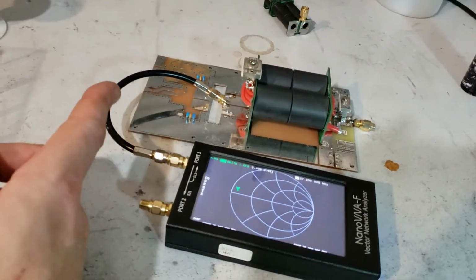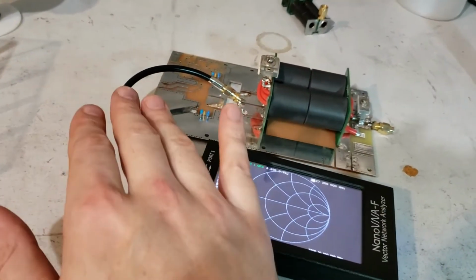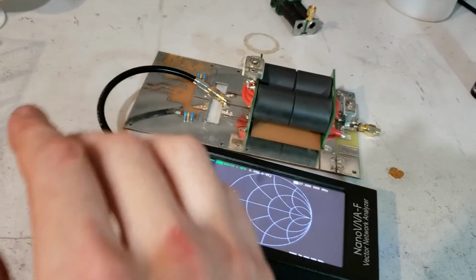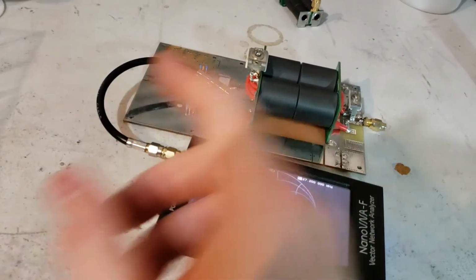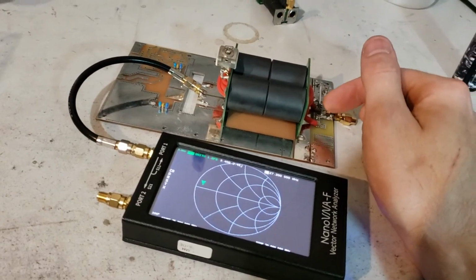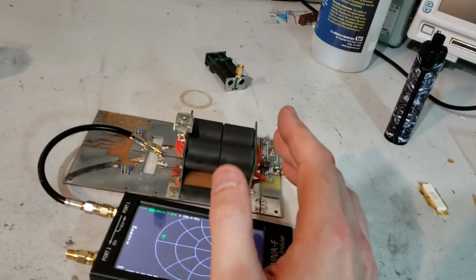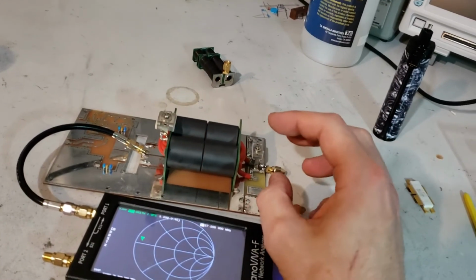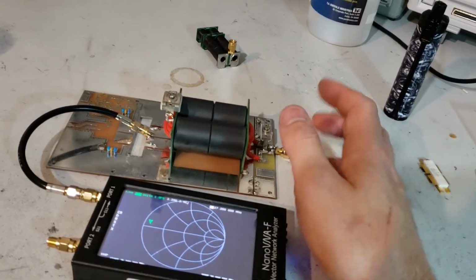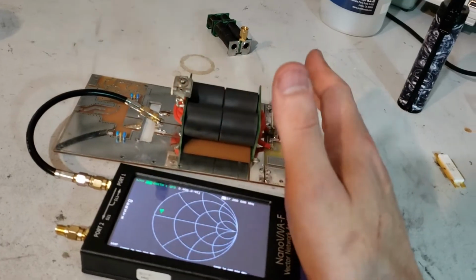If you're putting 1 watt in, and you've already got your input transformer reasonably well tuned, you put 1 watt in, and you tune these capacitors to get the maximum power output with 1 watt in. And then you go up to, say, 5 watts in, and then you check your tune again. You'll notice it's different.